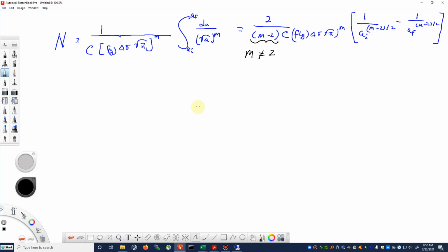Usually these fitting constants are not unique. Okay, so you'll often see this formula written down, and then you just don't take m equal to 2. We've assumed that we have a constant geometry factor, a constant stress range. Of course, pi is constant, and then here we have it to the m power. Here's the C. The C is usually a fairly small number. It depends on if you're in meters or millimeter type units. So I'm going to put here, watch your units.